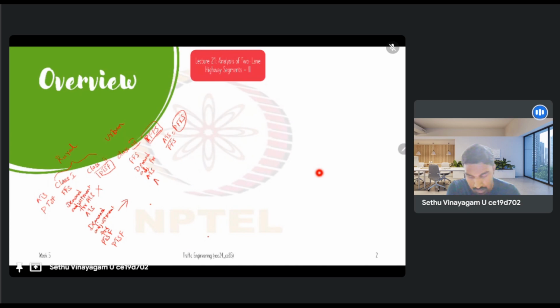So we do the demand adjustment, then get the ATS, then calculate PFFS, and then go for the LOS determination, right? So those are the steps involved, right? So this is the overall framework or the methodology that we use. So that was seen. Then we looked at the detailed computational steps, right? So what are the adjustment factors involved in each of these steps, which tables from the HCM that we use. So all those were explained.